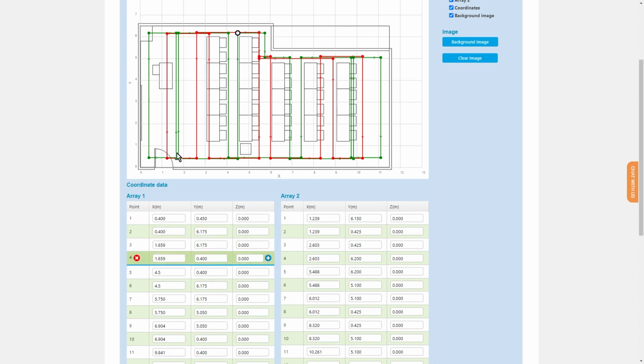And there we go. Finally, on the top left here, I'm hitting another obstruction, this pillar in the corner. Now, I could move this entire wire in, or I could have added a bigger gap when I was setting up the original automated design. I would always recommend getting the automated design as close as possible to what you want as you can.